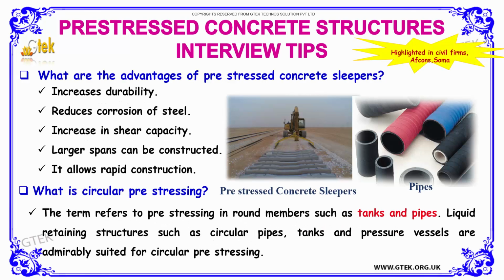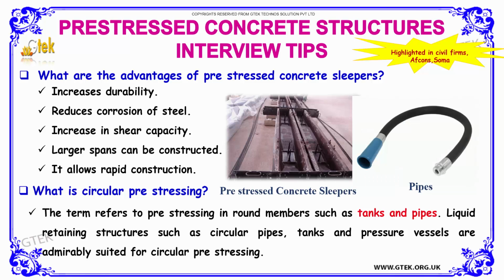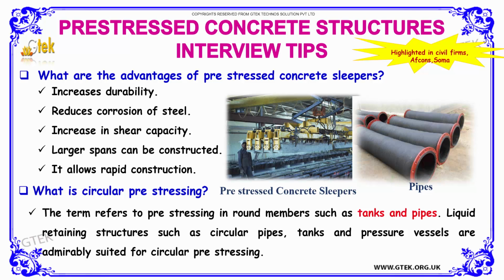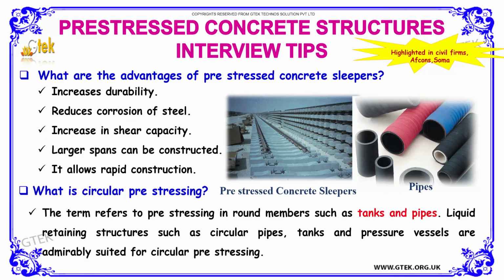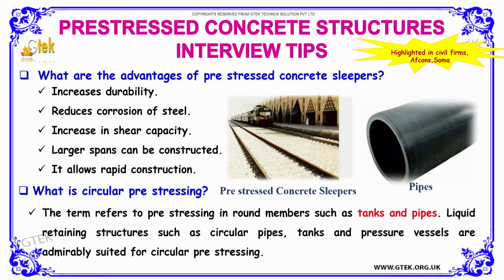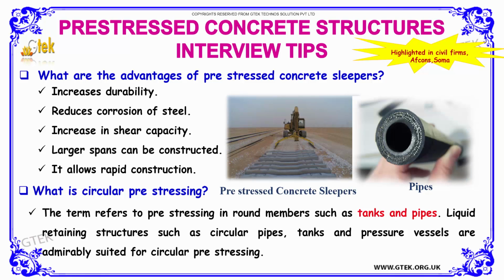We'll move to the next question. What are the advantages of prestressed concrete sleepers? The first advantage is that it increases durability. The second one is that it reduces corrosion of steel, followed by an increase in shear capacity. The next one is that larger spans can be constructed, and the final advantage is that it allows rapid construction. So these are the advantages of prestressed concrete sleepers.